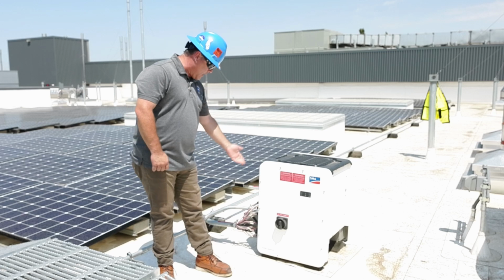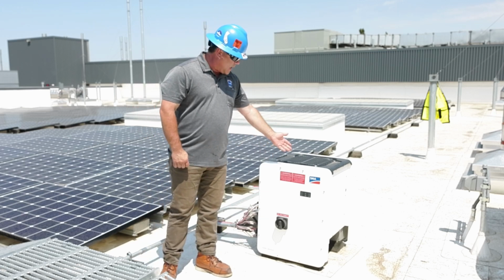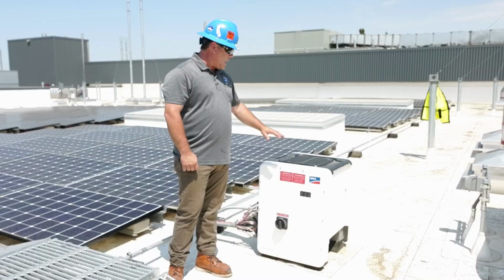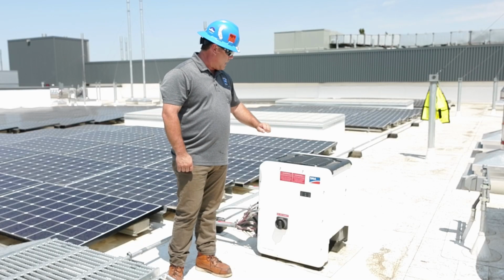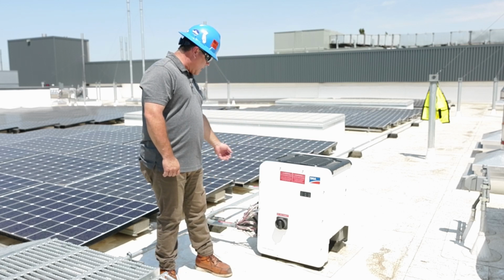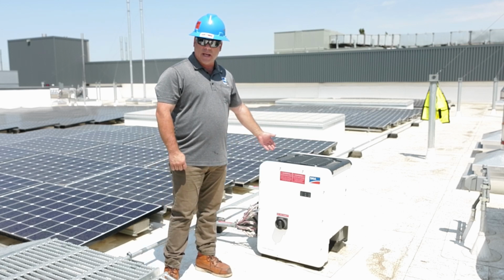We can see if there's any damage on the cables, any damage, any obstructions on the ventilation, any of the disconnects are off or on. And that's just by visually seeing it. We recommend that you clean it up. Make sure nothing is blocking any of the airways. Cables are intact. The AC is not damaged.